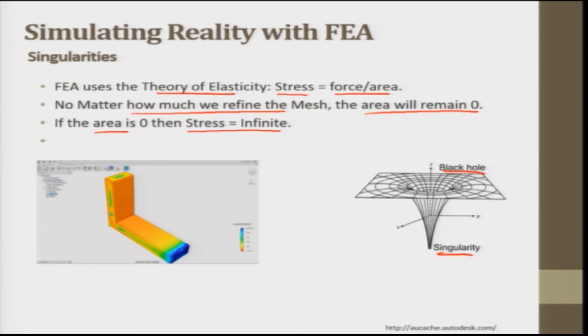So these are certain issues that a finite element analysis person faces. There are certain errors that could happen while we are conducting this FEA, finite element analysis. The modeling errors due to simplifications: we try to model for the real world and yet are not able to do it 100%. More simplifications sometimes lead to error. Sometimes discretization errors that result from the creation of the mesh, where the discretization or the division of the mesh is not proper.